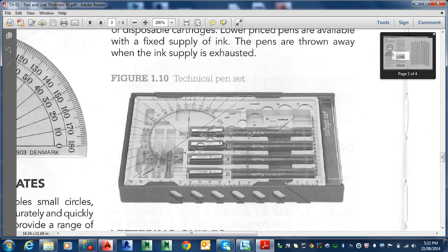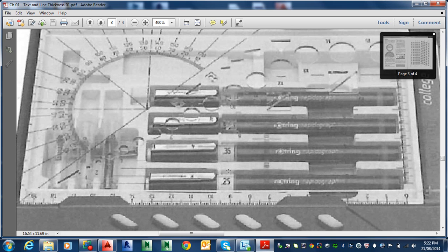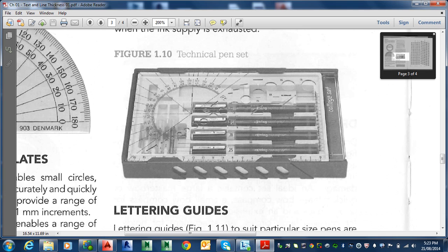And a lot of CAD, a lot of drafting officers, when they moved across, they brought their own habits. Basically, all they used is 4 different sizes of pen to draft with. So you can just make out 0.25, 0.35, that would have been 0.5 and 0.7, and that's all we really used. And you'll see that in the standards as we come through. Even the standards were done before CAD.